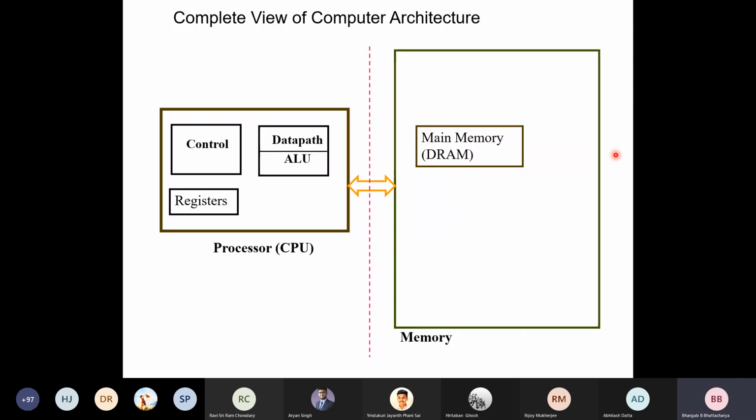The main memory which we usually refer to is a little slower, because the memory technology here is called dynamic RAM. So these are not flip-flops. Here, some transistors are used, and the bit 0 or 1 is stored as a charge, depending on whether the capacitance is charged or not. And therefore, the access of DRAM is slower, whereas the access of registers is faster.